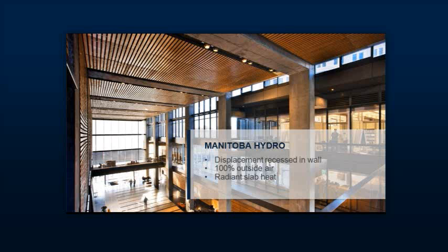Now, there was one casino in Milwaukee that showed a reduction of smoking particulates in the displacement part of the building compared to the mixing part of 50%. Now, I don't know that there's anyone that knows what an acceptable level of smoking byproducts are, and I don't. But I do know that from an occupant's perception, even though they're smoking in close proximity, you're really not aware of the fact they're smoking inside these structures.